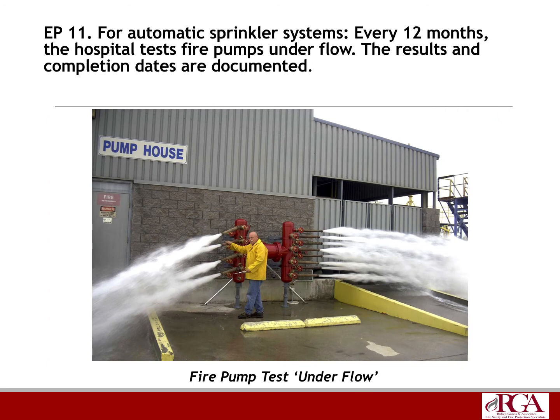EP11 for sprinkler systems, every 12 months, the hospital tests fire pumps under flow. The results and completion dates are documented.